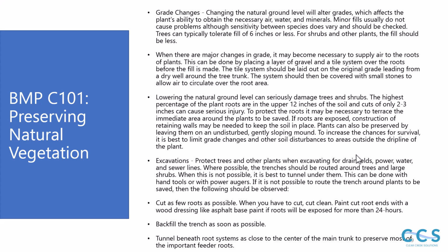Excavations: protect trees and other plants when excavating for drain fields, power, water, and sewer lines. Where possible, the trenches should be routed around trees and large shrubs. Cut as few roots as possible. Backfill the trench as soon as possible, and tunnel beneath root systems as close to the center as possible.